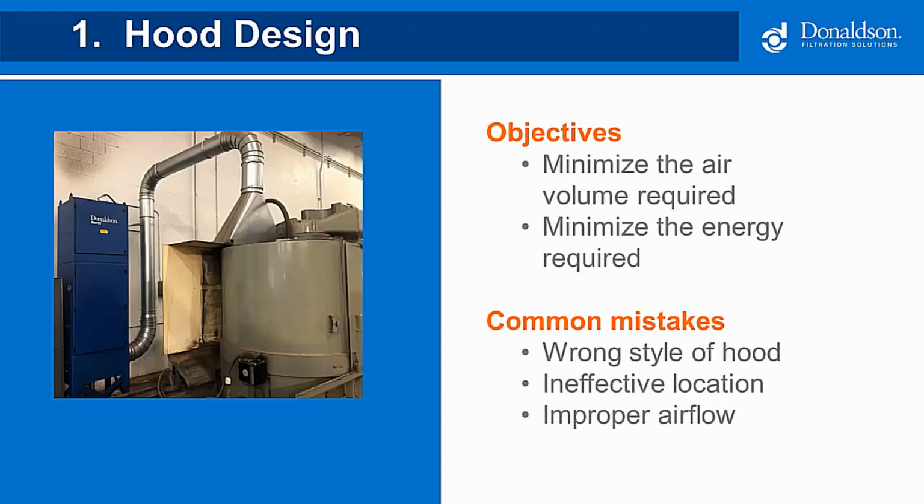So the first component of the system is the hood. This is a starting point for designing a filtration system, as this is where the airflow is determined for the process. Now, a well-designed hood is going to minimize the amount of airflow that's required to effectively capture and control the mist where it is released, while minimizing the amount of energy required to do this.